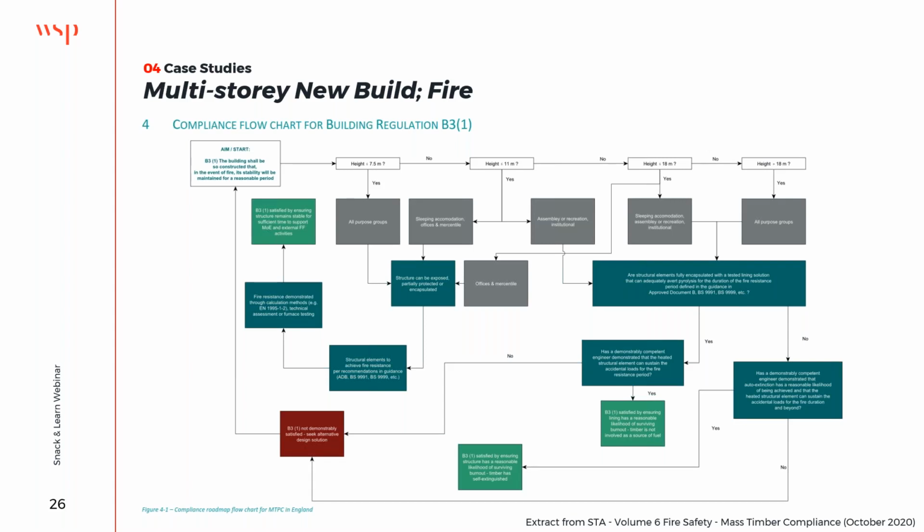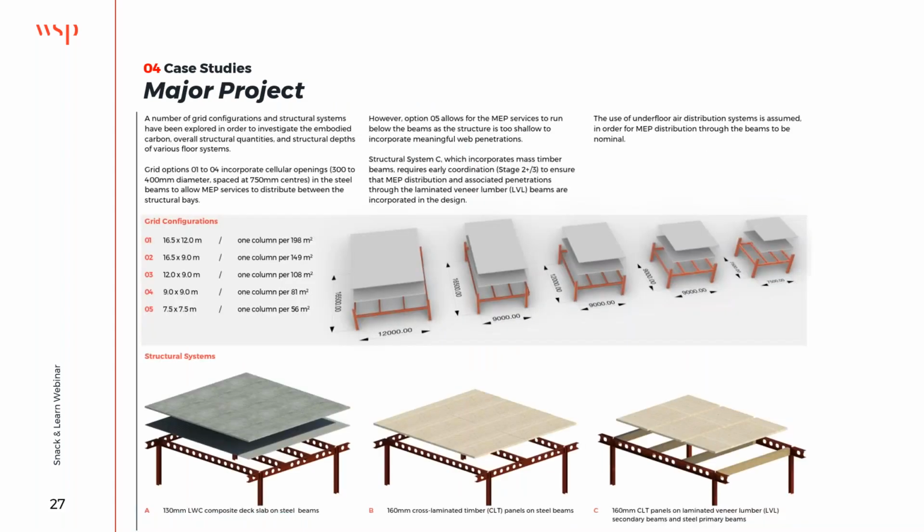So this third case study is a major project. This is 1 million square foot of office space with a 250 key 5-star hotel built on top of that. The first floor of the office space, or the first floor of the amenity level to the office space, is circa 30 meters above ground, and there's a 4-story transfer truss which bridges over a major infrastructure hub with lots of buried people movement assets below the site, and also a listed element as well.